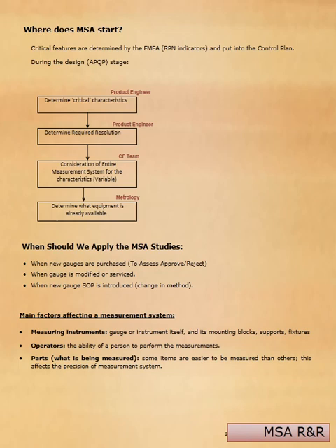When should we apply the MSA studies? Normally when new gauges are purchased, when a gauge is modified or serviced, or when a new gauge SOP is introduced.